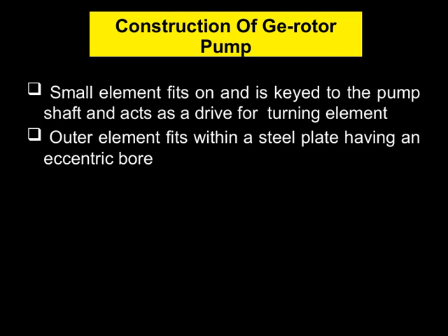Now let's take a closer look at the construction of the gerotor pump. The small element you'll notice fits directly onto the pump shaft and is keyed to it. This means it's securely attached and acts as the drive for the turning element. Essentially, it transmits the rotational force from the shaft to the other parts of the pump.